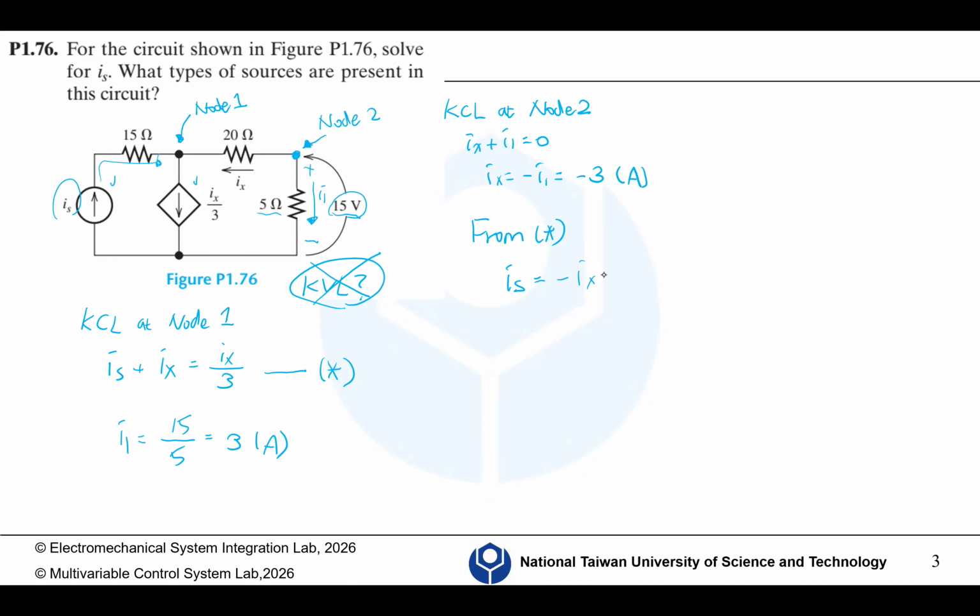By looking at this circuit, a ground has been given to you. So this is 0 volt. Usually, we connect the ground to the negative terminal of a voltage source. But in this problem, it doesn't have a voltage source, so we can define the ground at any node. Here, we just put it here randomly.